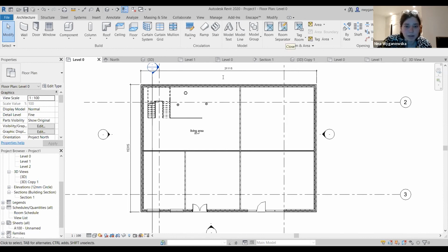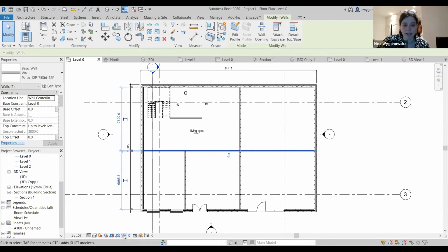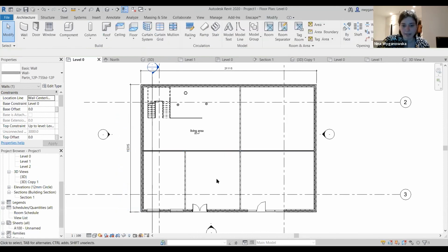Was going to ask about layers and isolating elements or diagrams. So, isolating elements, just as I said previously, you have a temporary isolation. I can isolate an element or I can isolate a category. You don't have something called layers in Revit at all.